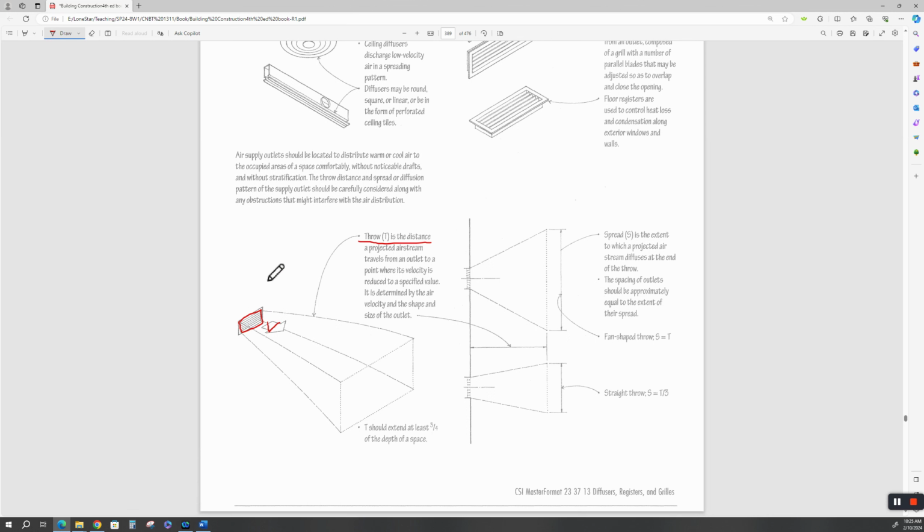And if you notice the ISO of that ductwork up there, as it got further away from the air handler, the ducts got smaller. That's because the velocity had to be increased. You got the same air pressure, and that goes back to your air balance. You can't run the same size duct all the way through, or you won't have any air velocity at all at the end, because you'll be sucking it out all the way down the run, right?